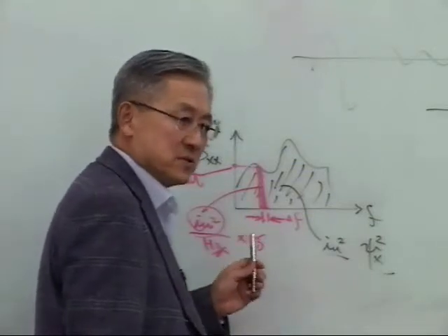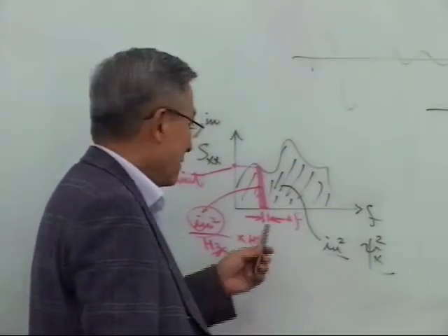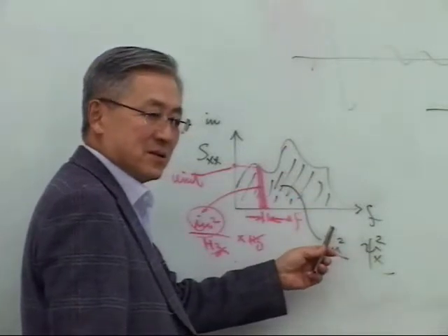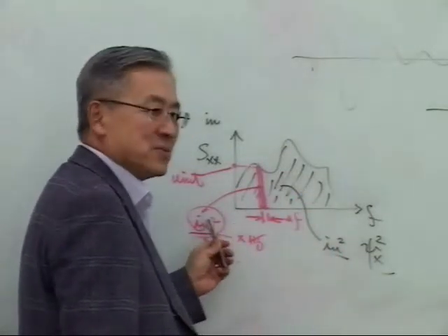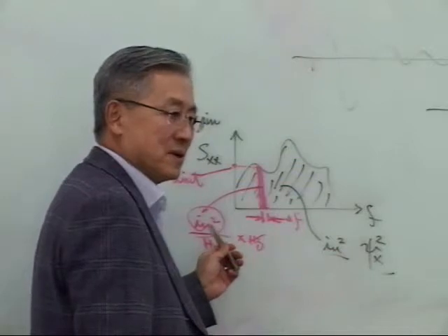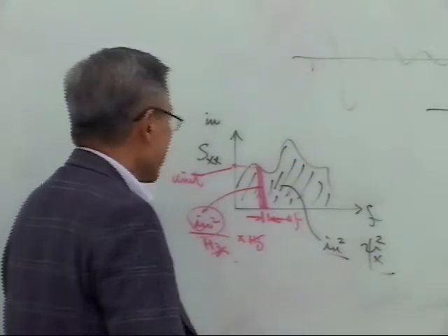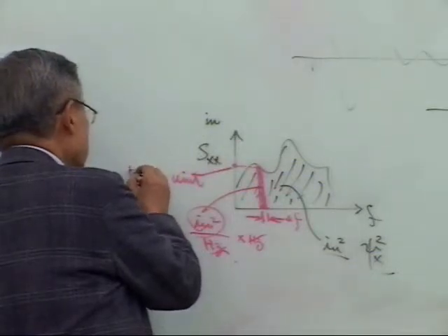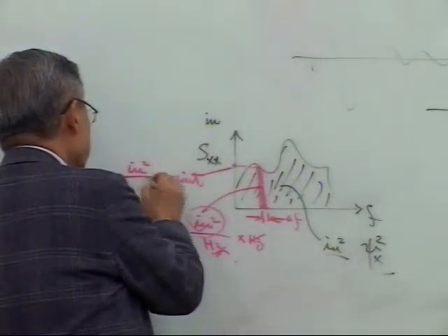It's really always you have to divide by hertz. Otherwise, when you calculate the area, you don't get a mean square value. Got it? So the unit in this case should be inch square per hertz.